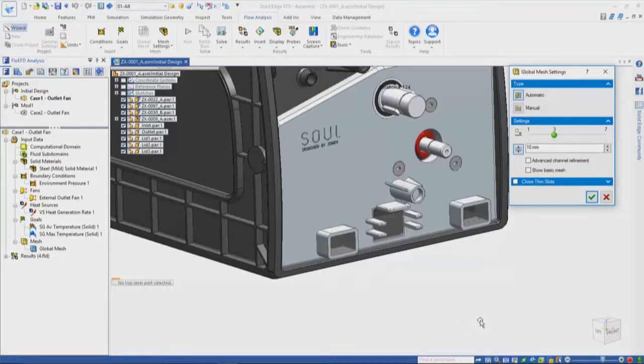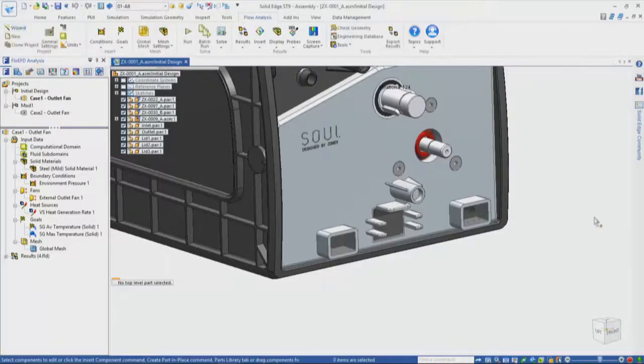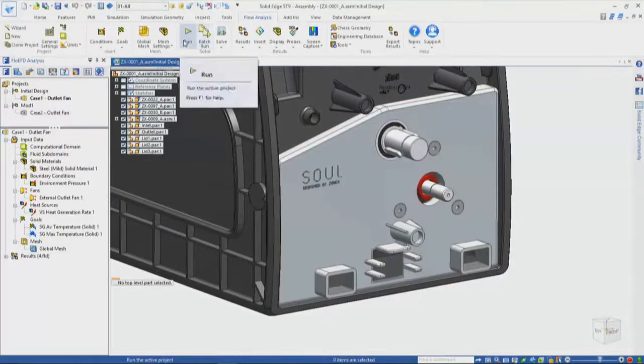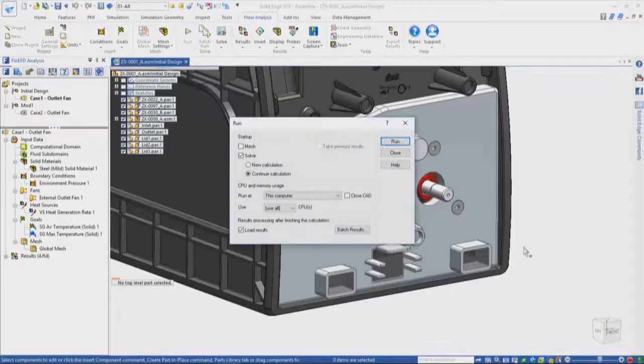As you move that slider bar to the right, that would build you a finer mesh. And the trade-off, of course, is resources and runtime with that. So that is the way that you, at least at the top level, control the meshing. From here, the model is set up, and you'd be ready to run it. You would pull up this run GUI, and you would go through, and if you launch it, it would mesh the geometry and then step into the run and solve it out.